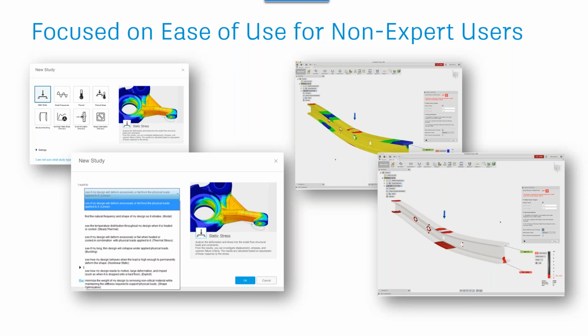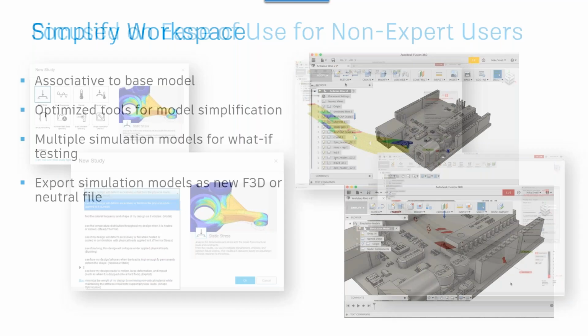And as you enter the simulation workspace into a study type, it will also guide you through the different steps which you need to set up during the simulation setup process. So you need to set up your material, set up your loads and boundary conditions, and then basically solve it. So it's a really simplified, guided process for the non-expert users.